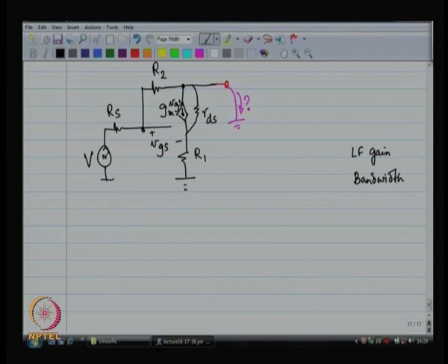All right. So, let us say that the voltage at this point is V1, the voltage at this point is V2, okay, and then I have got to write out two Kirchhoff's current equations. So, I have got V minus V1 by Rs, that is the current over here, that should be equal to V1 minus 0 by R2.